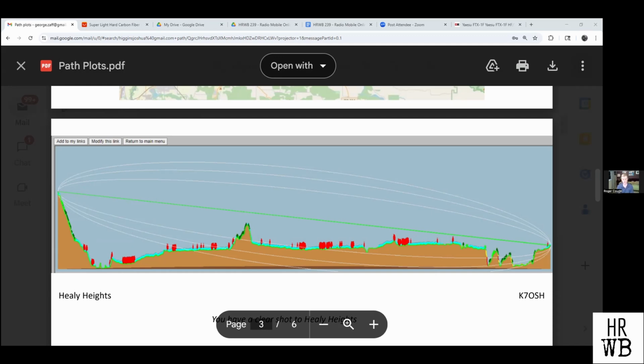there is a rule that most engineers apply, which is to let 0.6 of the first Fresnel zone pass. So normally when you drive on the road and you see these dishes on the towers, they are not necessarily on top of the tower. One is on top and the other is in the middle or a third.